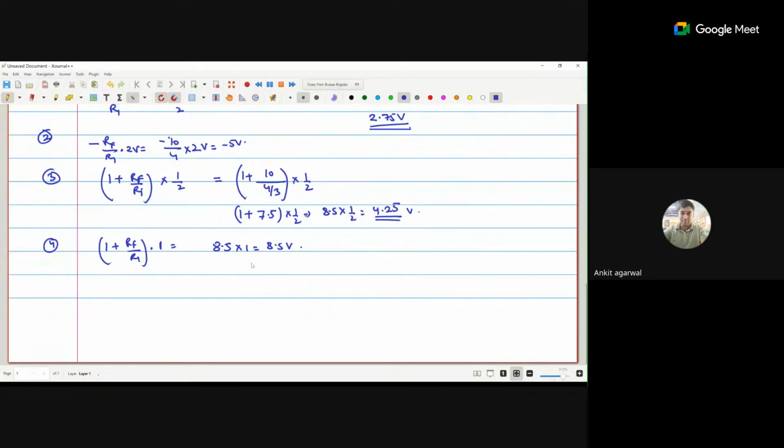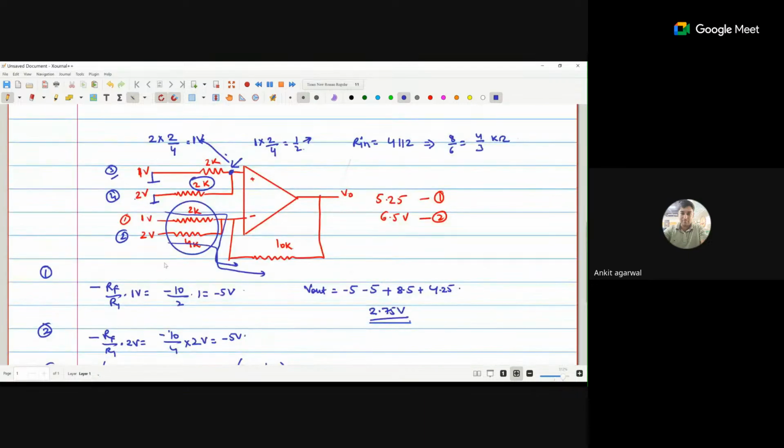Okay, so this type of mistakes, remember that negative, no effect, but positive resistance if connected in parallel, so they will create an effect. On the negative side, no effect. Why? Because on the negative side there is a way to pass the current to V0. They have a path to flow the current till V0, but on the positive side they don't have the current, so we have to find out this voltage. Now this voltage is equal to this voltage. That's why these parallel resistances at particular points will create the effect.